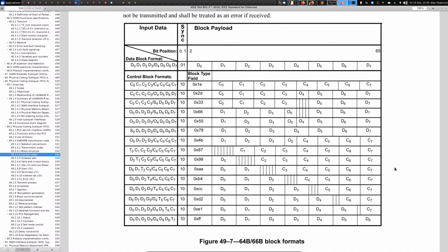So one thing that these line codes will do is ensure that the result has a similar number of ones and zeros. So 8B10B and 64B66B use very different techniques for doing this. 8B10B is a more deterministic encoding scheme. And as a result, they actually keep track of the running disparity, and all of the symbols are carefully designed so that they have almost the same number of ones and zeros. Some do, some don't, and the ones that don't use the running disparity to select which symbol to send, such that you can maintain the DC level at 0.